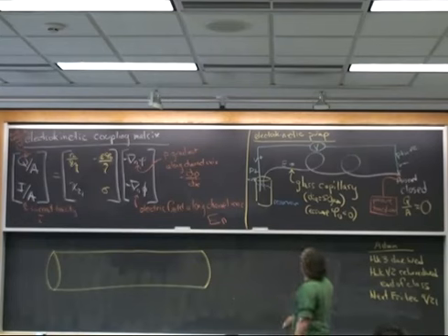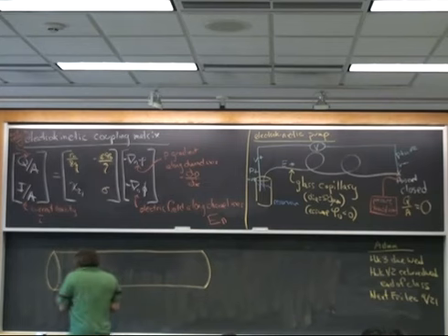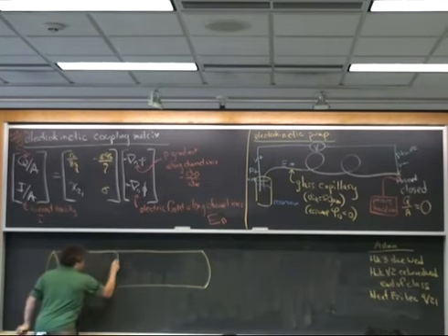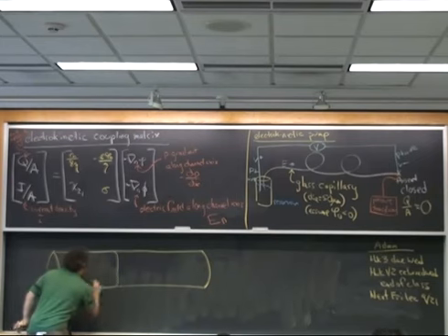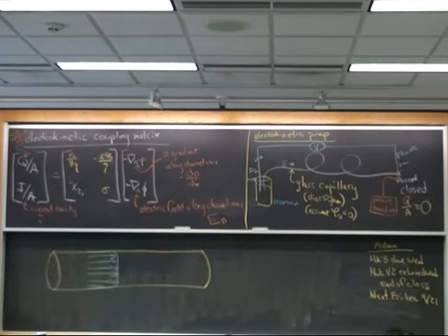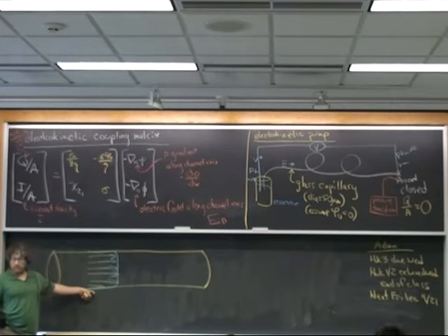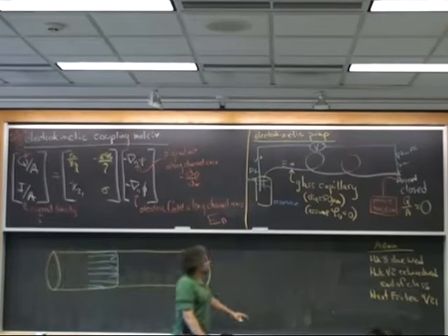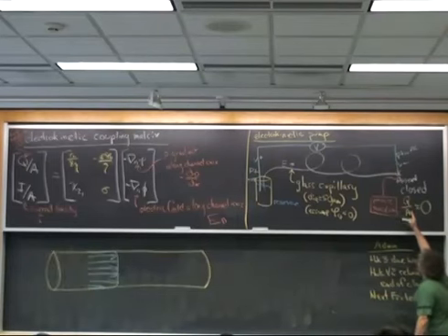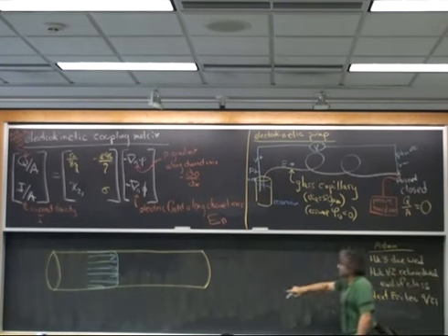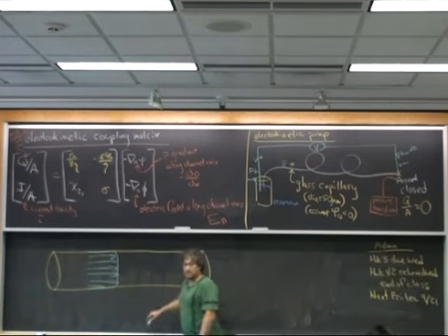Okay, so I have a tube. I start out by applying an electric field, as denoted by the green line and the platinum wires. When I do that, I generate an electroosmotically induced flow. That basically looks like this, right? Now this flow has a net mass flux, which means that the flow starts moving from left to right, right? That can't be consistent with the fact that I have a closed end, right? So this is only sustainable if I have some finite compliance in the system.